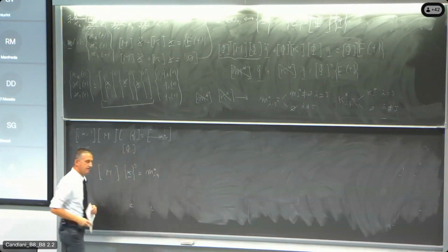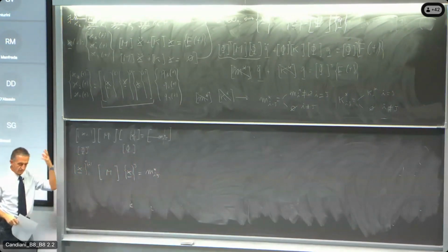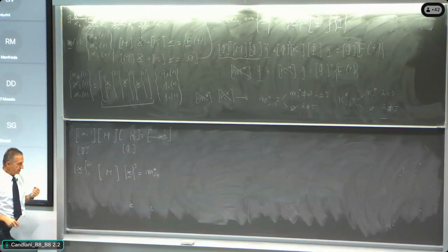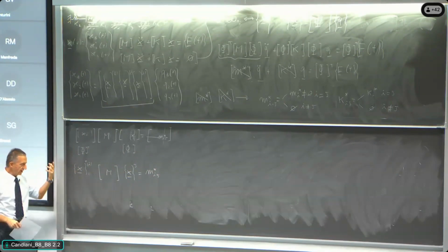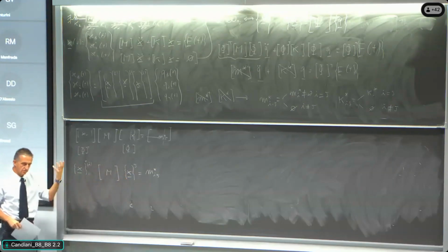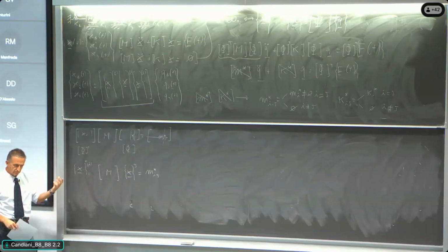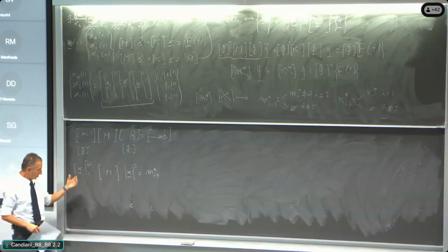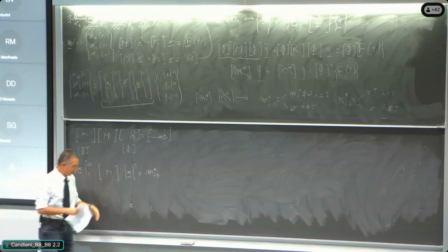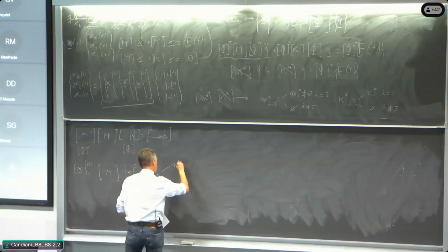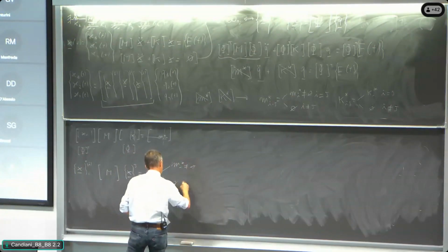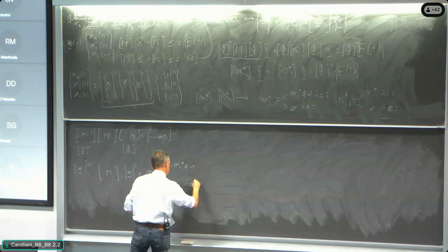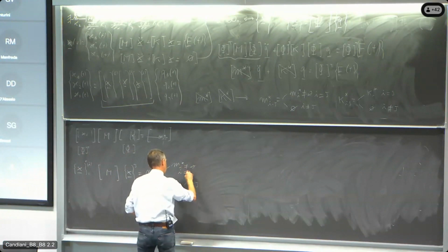All right. So the orthogonality property of the transformation in principal coordinate is that the ith eigenvector is orthogonal to the jth eigenvector through the mass matrix and through the stiffness matrix. So if that is m i star different than 0, and 0 for i different than j.